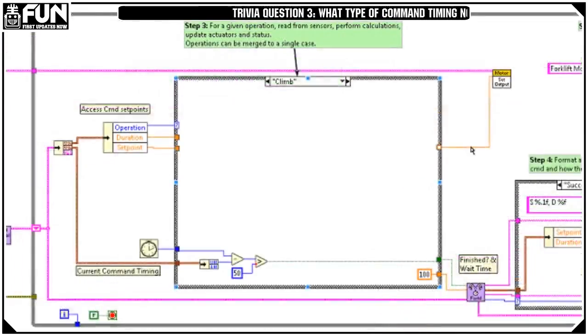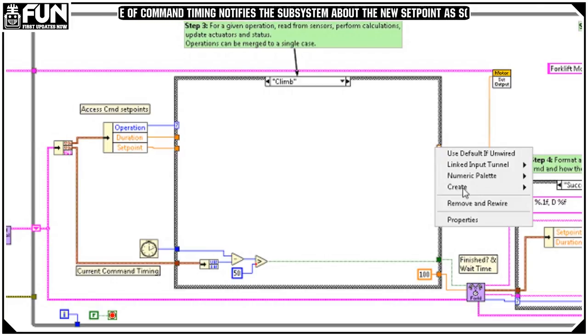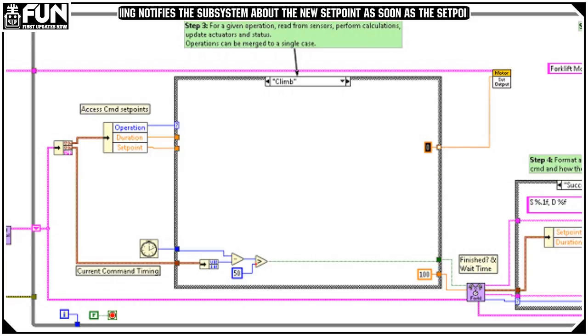And then for our motor output, say we did some testing and we found that when we go to climb, we just need the motors to operate at 90% of their total capacity the whole time we're climbing. So we're just going to go ahead and put in a 0.9, and the whole time this climb command is running, we're going to be operating at 90% motor capacity. This is a good idea to not operate at 100% motor capacity, because that's how you can get to brownouts and things like that, which are not good when you're trying to climb a 7-foot tower.